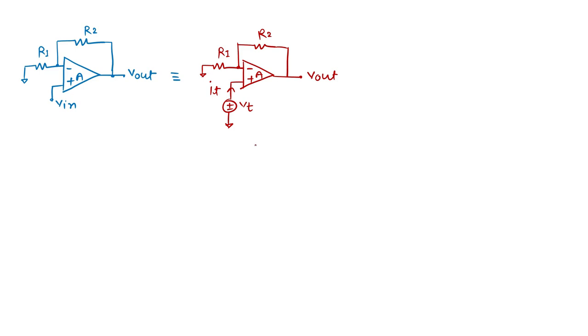Here one can think, if you are applying a test source in the non-inverting terminal, and if I am considering the current going inside to be 0, then Rin simply comes to be infinite. So this is the ideal case. Let me consider that there is already an input impedance of the amplifier. Why am I considering this? I want to tell you what the net expression should be if an input impedance is given, and what the input impedance should be when we are looking from the source.